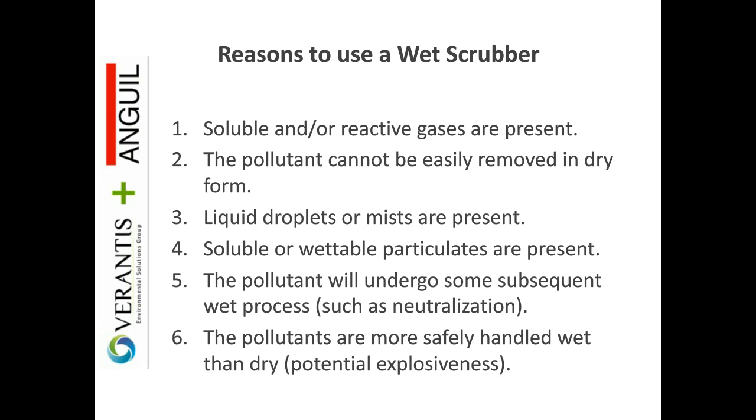If the pollutant cannot be effectively removed, or not effectively enough, in an alternative dry form, this comes up from time to time. Sometimes these scrubber efficiencies are required to be 99.9% and beyond, and sometimes a wet system is able to drive to a little bit higher efficiency. If you already have liquids or condensation present in the gas stream, whether that's your contaminant or not, a wet system is typically going to be very well able to manage that from a material handling standpoint and